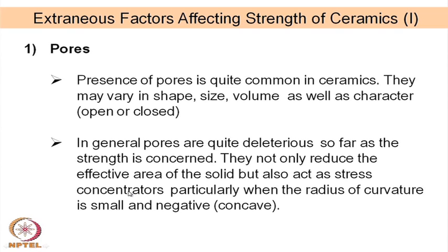So, although pores are really not cracks, there is some amount of openness within the monolithic structure of the ceramics, and therefore, the pores not only reduce the overall area through which the load will be borne, but under certain circumstances can also act as stress concentrators just like cracks.